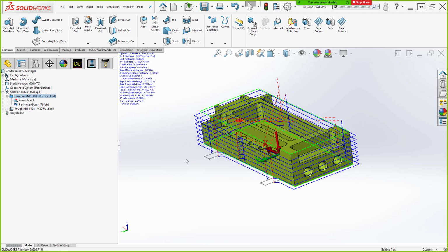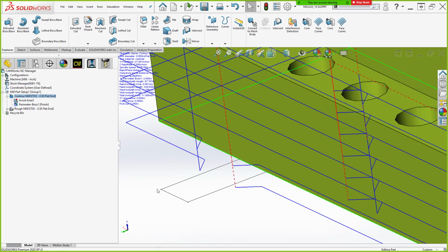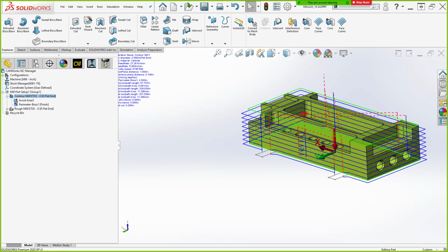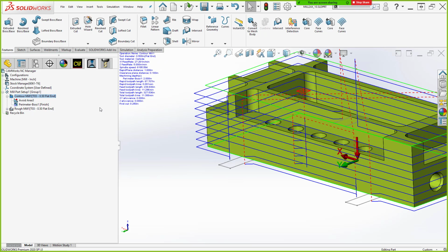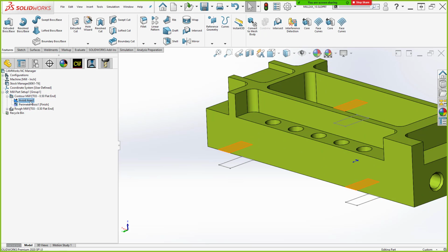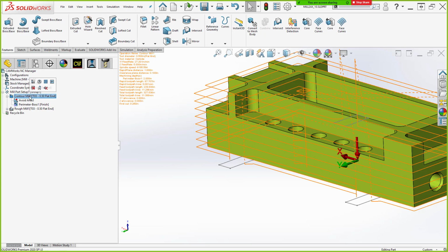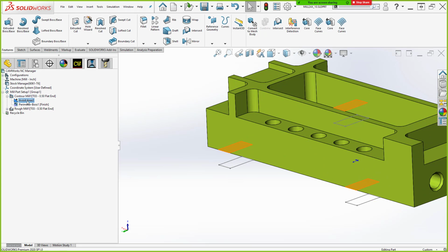You can see the toolpath right around those clamp areas, right? Those last two toolpaths, those last two depth of cuts kind of stopped, right? And we have these retract moves that kind of go over them and reset us and go back around. So once again, the avoid areas are contained underneath, right, the particular operation they apply to, right? So underneath that contour mill, now I have avoid area number 3, right? Because I've created a couple of these, deleted them. It keeps iterating in number.